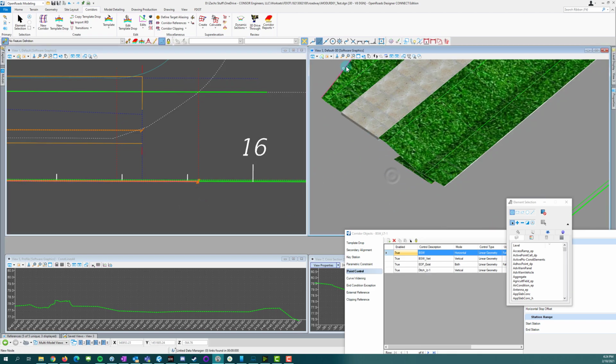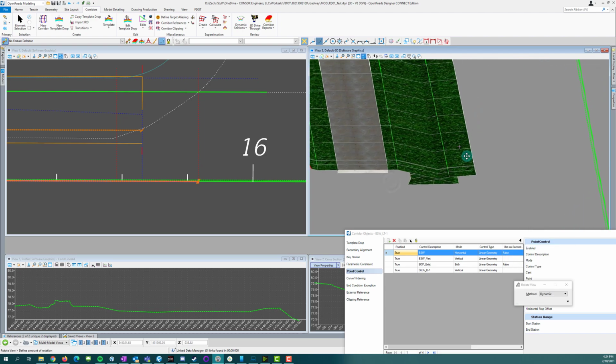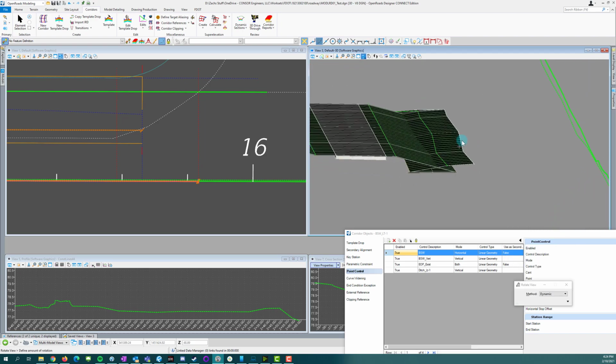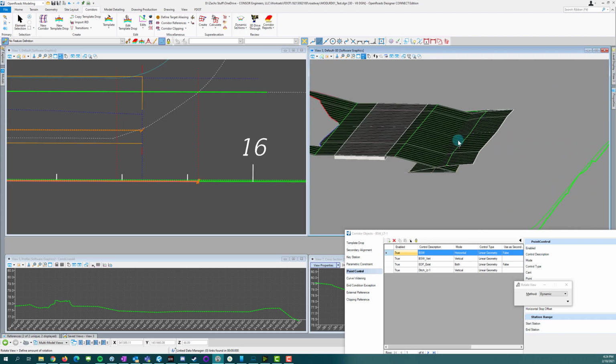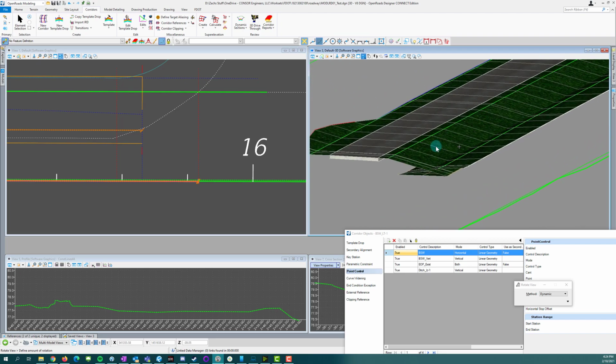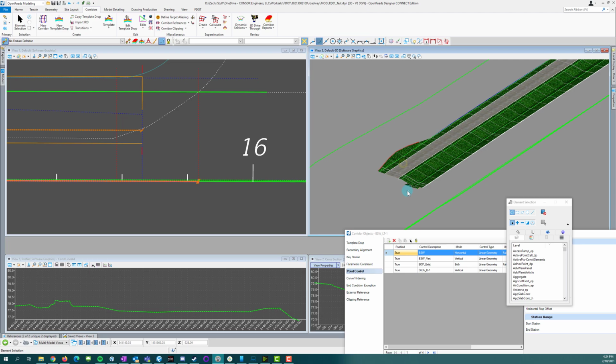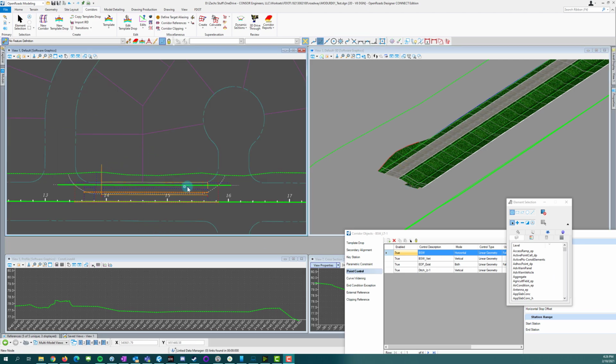All right, so first thing I notice here is our ditch is a little bit too low for the slopes that we're using. So I like our back of sidewalk. It looks pretty good. All right, so another thing I want to do is I want to be able to see where I'm tying down.